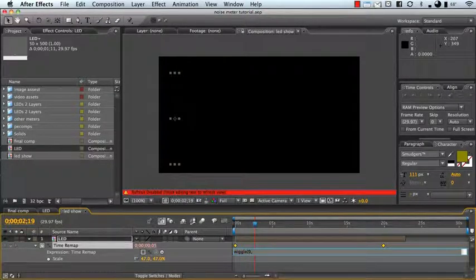So if you want it to wiggle like 15 frames, you have to give it 0.5, which is half a second. If you want to keep it easier in your head, like I do, I just enter in another math equation here, 4 divided by 30, because we're working at 30 frames per second, so that will be 4 frames. And don't forget that second closing bracket.